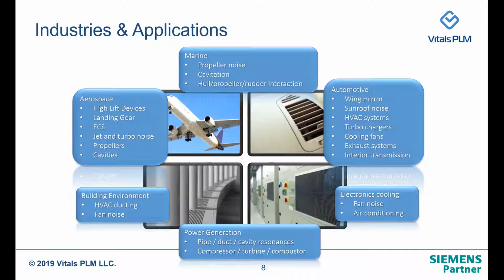ECS, environmental control systems, also have some noise issues. Jet and turbo noise: the flow coming out of the jet engines has a highly turbulent flow, and that becomes a source for the noise. Propellers and cavities are equally important in the aerospace industry for aeroacoustic analysis.